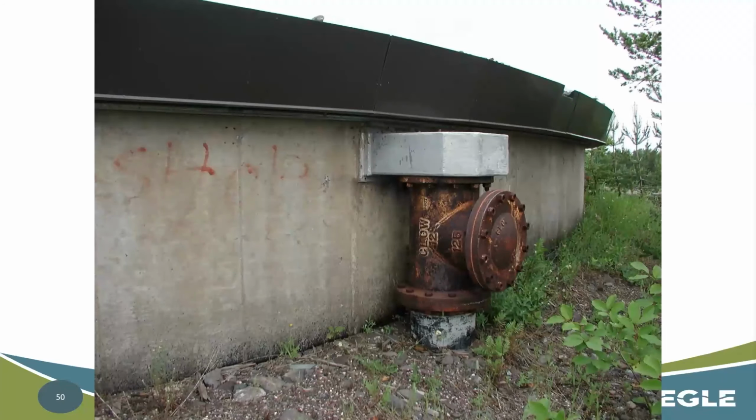Here's another example of a ground storage tank weir box. Now this is a ground storage tank, so it's probably not too much of a concern. But if this was an elevated storage tank, this kind of design might not be ideal. If you had some ice caking in there, ice formation could come up and basically block this outlet. So you're still having the same issue, and there's really no overflow because now ice is just sitting in this way. Luckily, it's a ground storage tank, so it should stay relatively warm enough where that weir box won't become an issue.